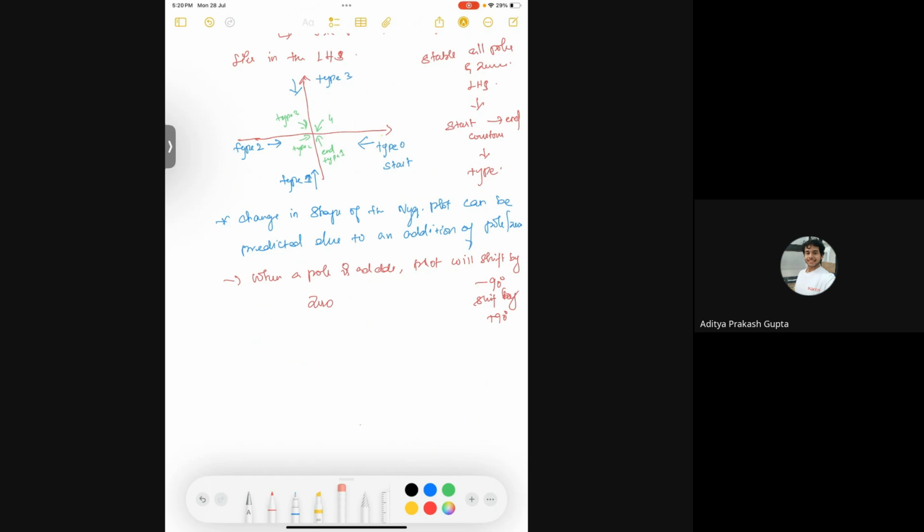If you see a Bode plot, it visualizes the same system using magnitude and phase plots. But a Nyquist plot gives it to you in a complex plane. It is evaluated based on phase margin and gain margin, where the Nyquist is calculated using the encirclement around the -1 value. The Bode plot is basically used to design and tune controllers, for example PID tuning. But Nyquist is more towards analyzing stability.